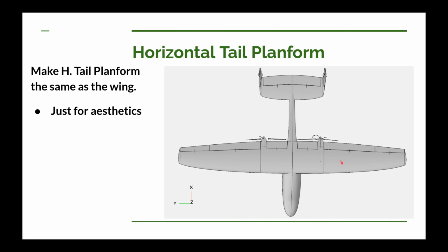And then also the sweep of the wing increases as you get out closer to the tip. Now the reason for that was to help make these trailing edges a little bit straighter, so I get to have a long flap here. And that also causes this main leading edge to trail back a little bit more than it would on an elliptical with a straight 25% chord.